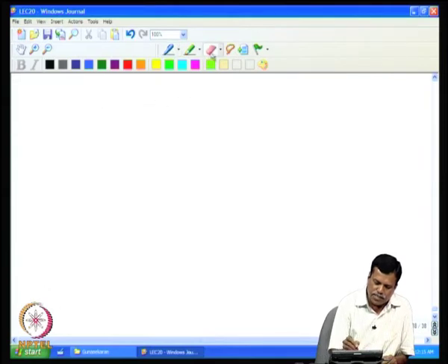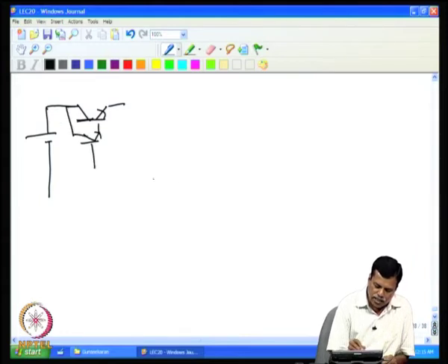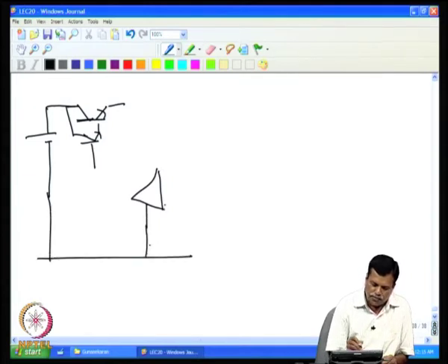I will not spend much time on this, I will just show you how this regulator is made. So, you take this voltage, then we will have a regulator in here, and then we have used an error amplifier for this purpose. An operational amplifier was used as an error amplifier, and we also used one Zener to start up the current.